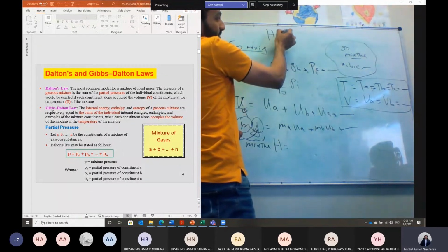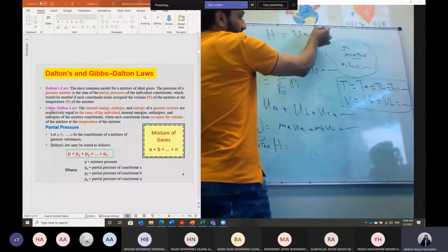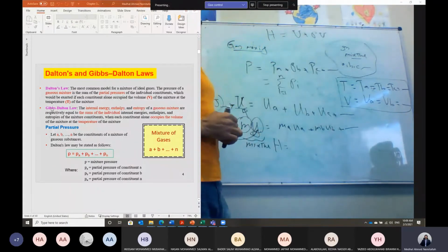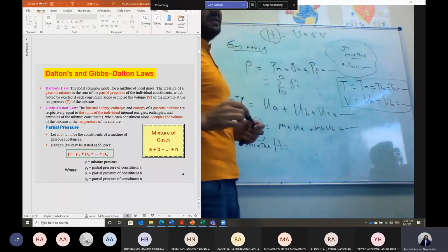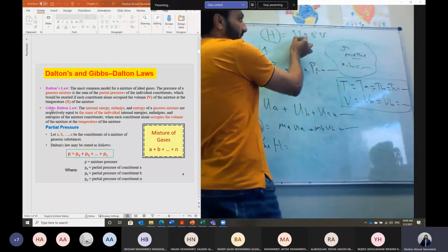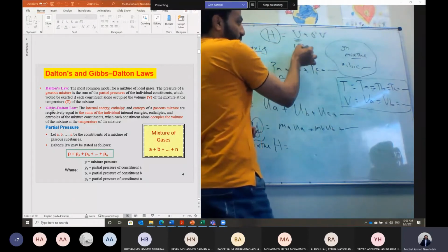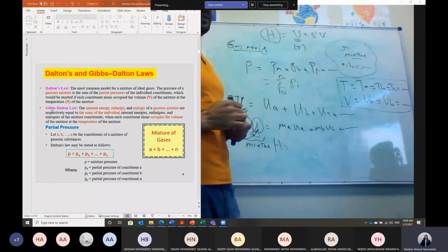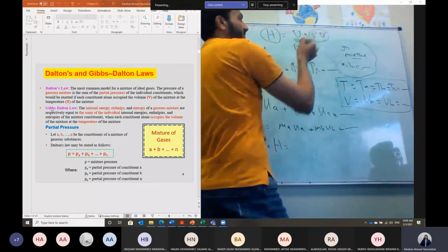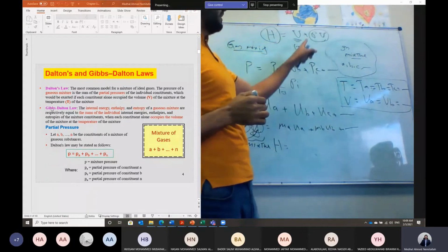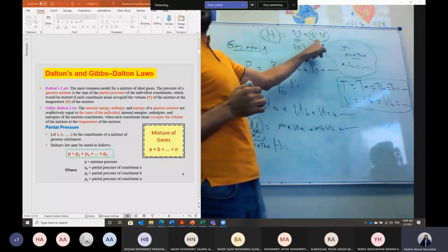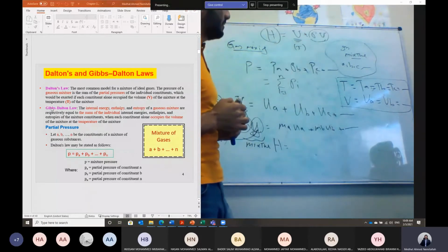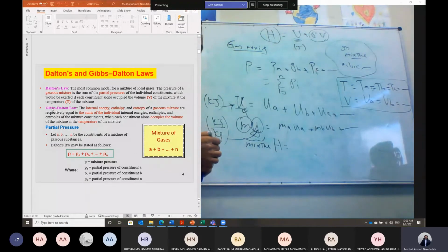Enthalpy is defined as what? The internal energy plus the flow energy, which is pressure multiplied by volume. So enthalpy does not have any physical meaning unless it is the summation of the internal energy, which is mainly a function of the temperature of any gas, plus what we call the flow energy, because to have a flow we have to have a pressure in order to force the flow to go. So we call it the flow energy. Flow energy is pressure multiplied by volume in this case.